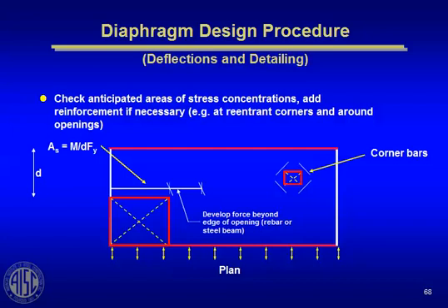If you forget that, and you get a high windstorm, you might find yourself with a diaphragm failure. And indeed, there's been very clear evidence of this occurring in high seismic zones in earthquakes, where the diaphragms just haven't performed because there wasn't a valid load path to get these shear loads where they needed to go.